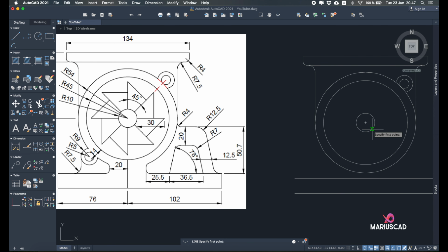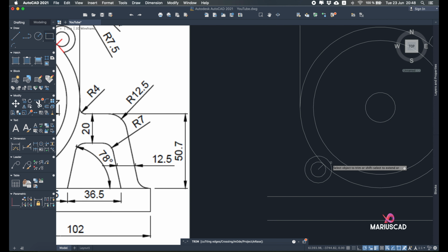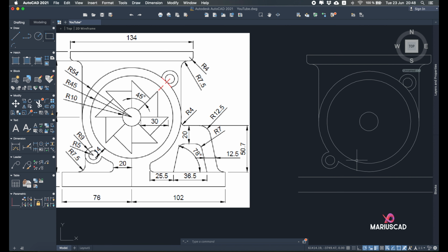In the other part is the same story. Again with the 45 units. But this time, go directly for trim. In this part you see, you must go with 5 units, the same direction. You can delete this one as well. Build a circle with radius 5, a circle with the radius 9. Start to trim. And you have exactly what you need.